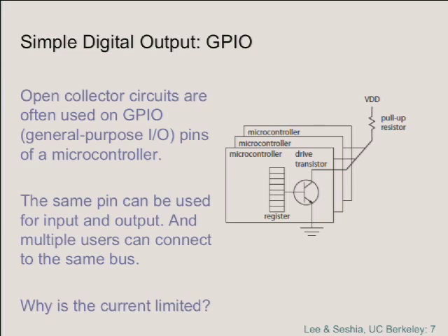Very simple. It's a little more complicated if you have a device that wants to initiate transactions on the bus, because then you need some arbitration scheme. So a bus will typically have not only address and data lines, but it has a few other lines that are used to manage the access of multiple devices to the bus. So one of those lines might be a bus request line. So what happens is you make a request by pulling a bus request line down low.